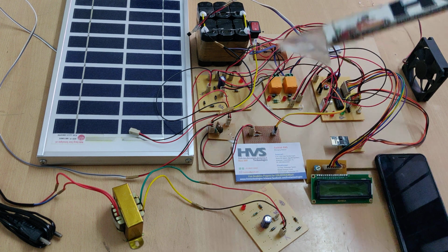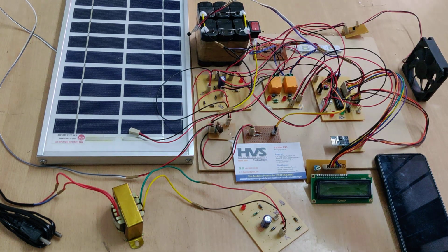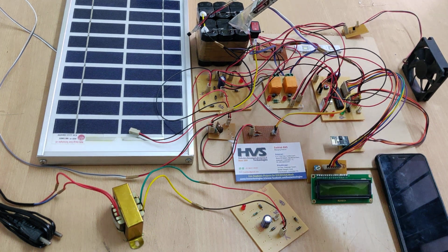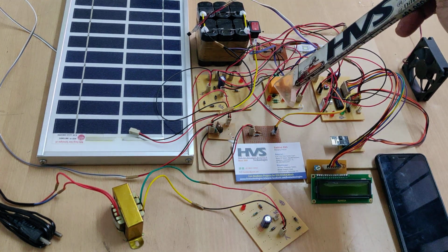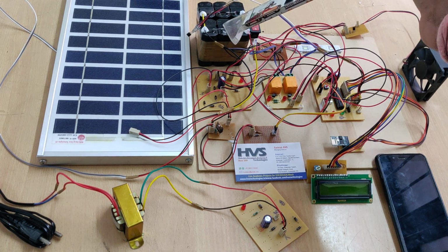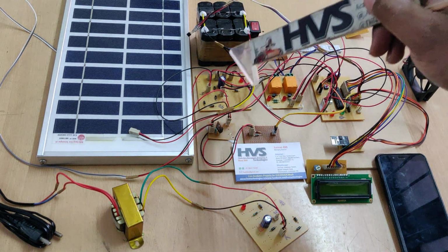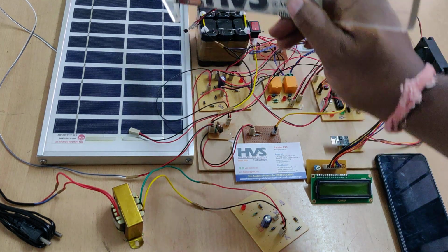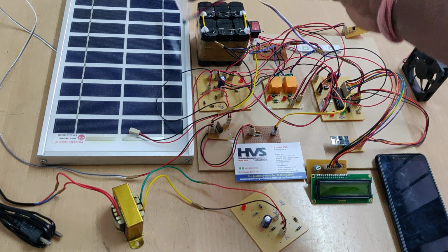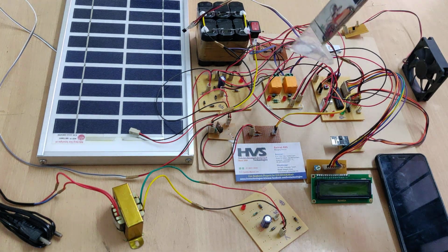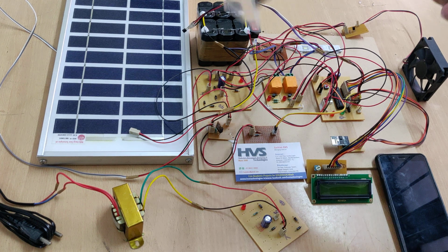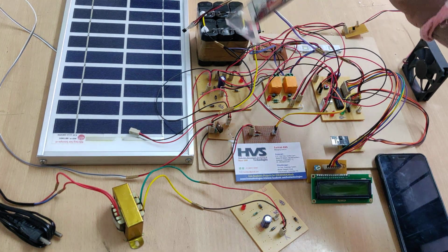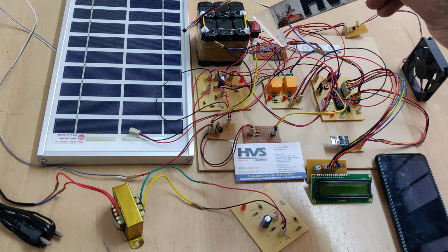So here the main purpose is, as we explained, solar panel voltage measuring and battery management with voltage set points. When it is below 11 volts, charger on; above 13.5, charger off, as well as while charging or discharging. If there is any battery heat up, that will be identified with the help of this LM35 temperature sensor, and we will set the temperature to 50 degrees centigrade. Then the microcontroller will isolate the charging voltage to the battery. So this is the main on off switch.